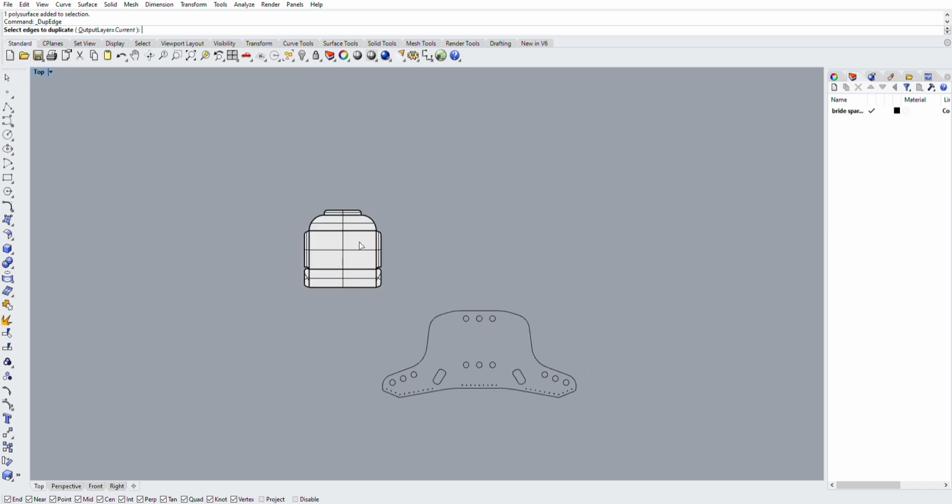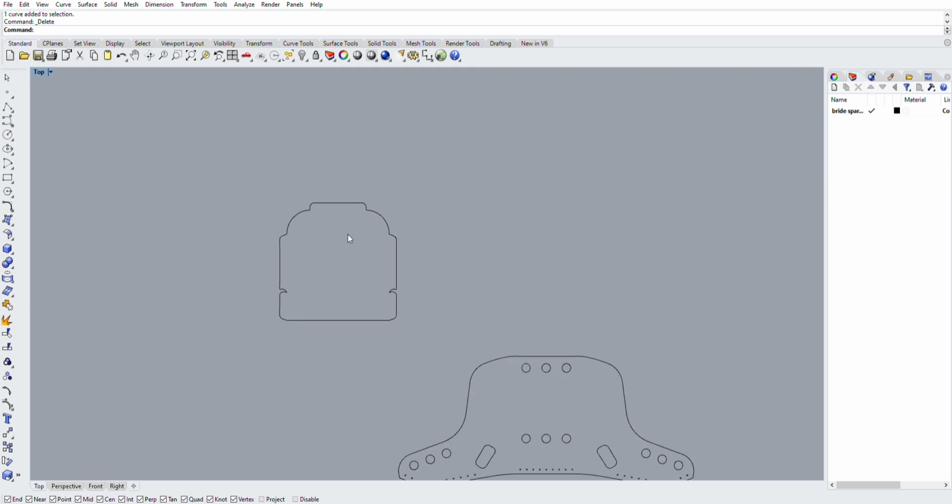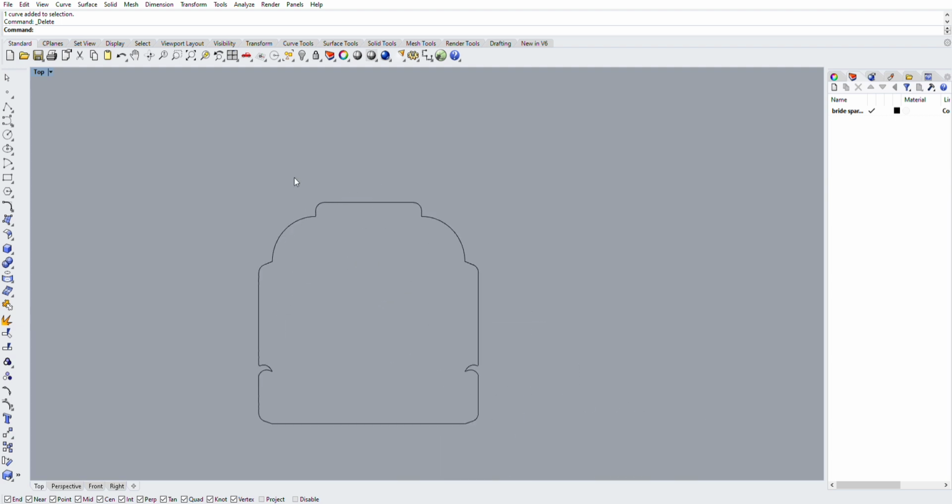We're going to do the same thing on this one and duplicate them, delete our surface, and go back in, and we can delete all of the cross lines here. Now, some of these would be bend lines. If we need the bend lines there, these ones all get bent on points, so it's not a big deal.